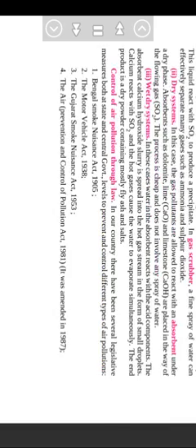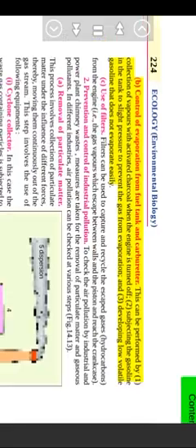B. Control of evaporation from fuel tank and carburetor. This can be performed by 1. Collection of vapors with activated charcoal when the engine is turned off. 2. Subjecting the gasoline in the tank to slight pressure to prevent the gas from evaporation. And 3. Developing low volatile gasoline that does not evaporate easily. C. Use of filters. Filters can be used to capture and recycle the escaped gases, hydrocarbons, from the engine, i.e., the gas vapors which escape between the walls and the piston and reach the crankcase.